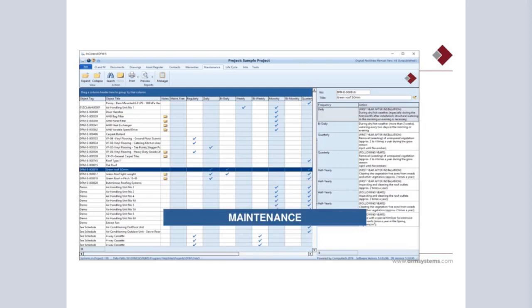As we collect information and operate the maintenance manuals, we're extracting maintenance requirements from that so that we can build a ready reckoner for the building owner, showing him everything he needs to do in terms of planned preventative maintenance on every component in the project, including, for example, the wall finishes or the green roof on the project itself.